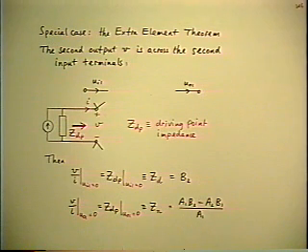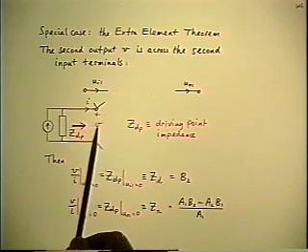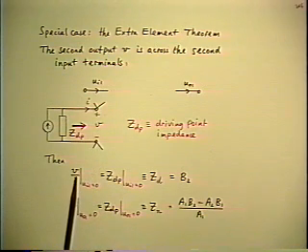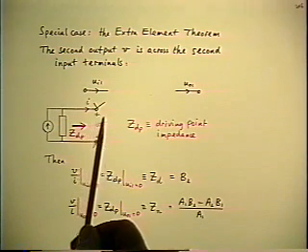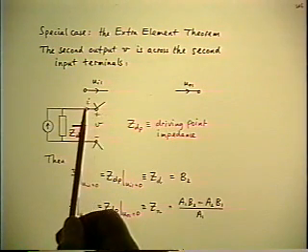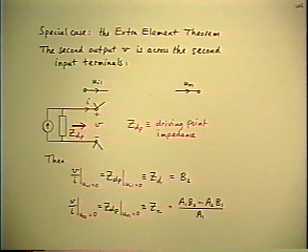The only difference is the interpretation of this ratio, this transfer function, because it is now a self-impedance, because it's the ratio of a voltage to a current at the same place. It's what the circuit theory people call a driving point impedance.